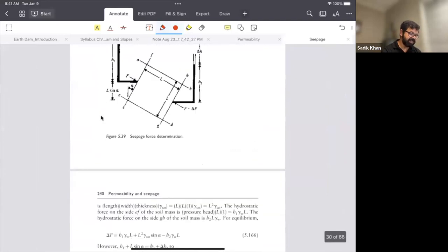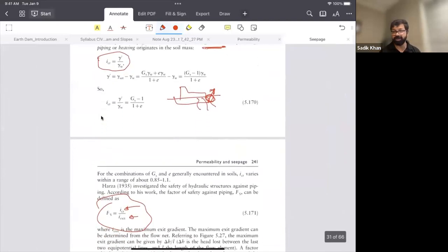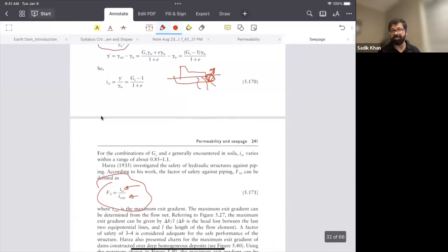Nowadays it's very easy in Adobe Acrobat Professional. In the PDF, you can do that. You don't need a ruler. You can just use the ruler command on there, and they have a scale. So you can set the exact scale, and then you can calculate that. That's very easy, and it's pretty accurate.